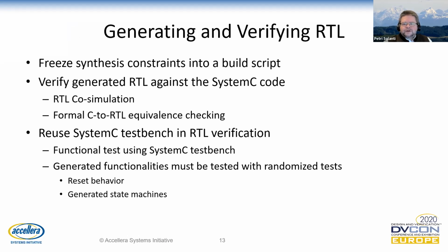The generated RTL is verified against the SystemC model using RTL co-simulation or formal C to RTL equivalence checking. If it passes the smoke test, it can be passed to the normal RTL verification flow with the SystemC test bench and coverage analysis data.